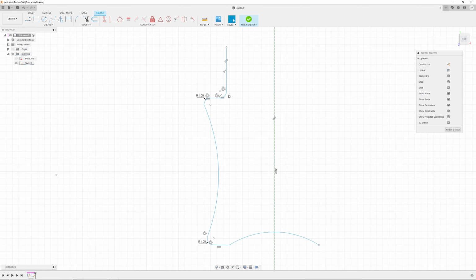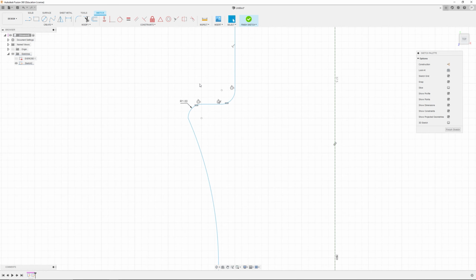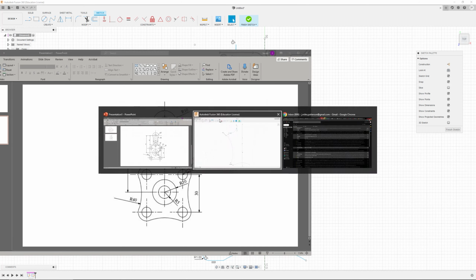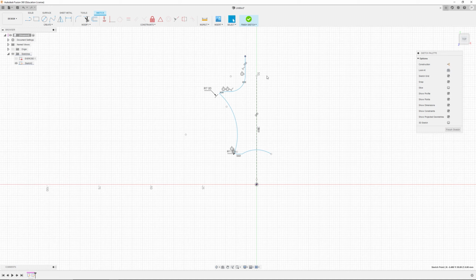Okay, so far so good. Do those flow straight into each other? It's kind of hard to tell. It says radius 6, radius 7. So this needs to be 7. You can see here now it's going to start scaling. So this is where I need to adjust everything before I put any more dimensions in. So this straight line needs to come up here.